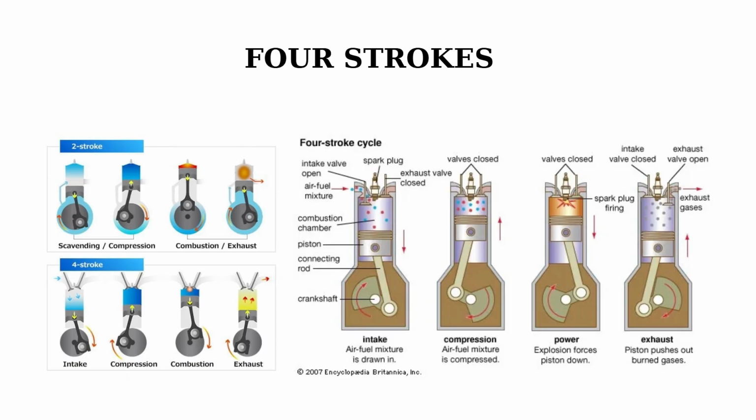Now, the compression stroke. We can say sıkıştırma zamanı in Turkish. After the intake stroke, the compression stroke begins. During this stage, the piston moves upward inside the cylinder. Both the intake and exhaust valves are closed tightly. This traps the air-fuel mixture inside the cylinder. As the piston moves up, it compresses this mixture into a much smaller space. This compression increases both pressure and temperature inside the cylinder.